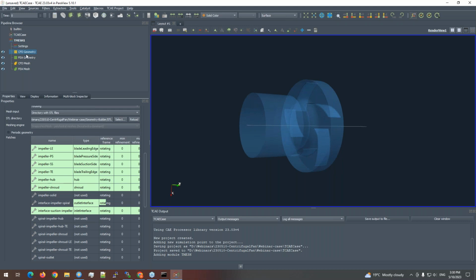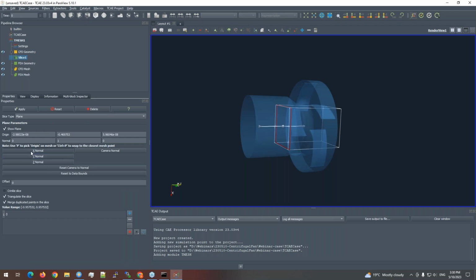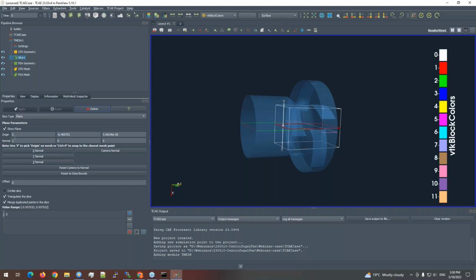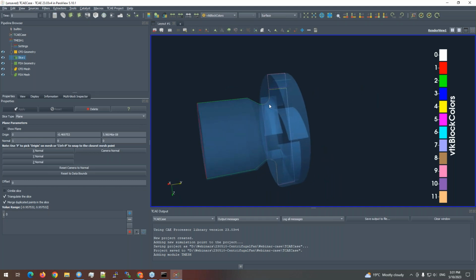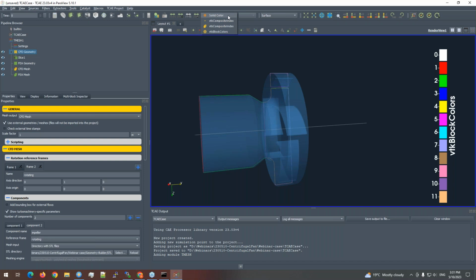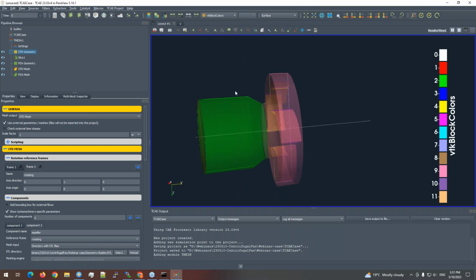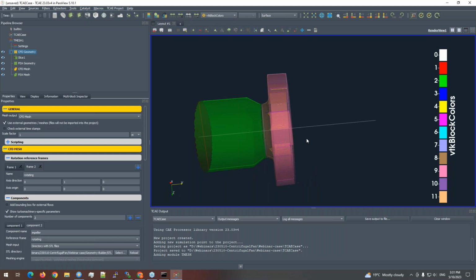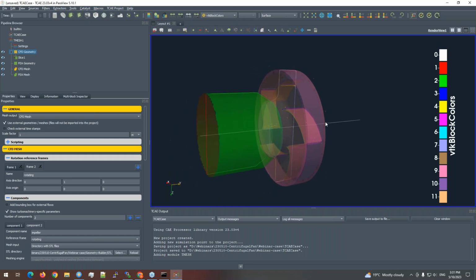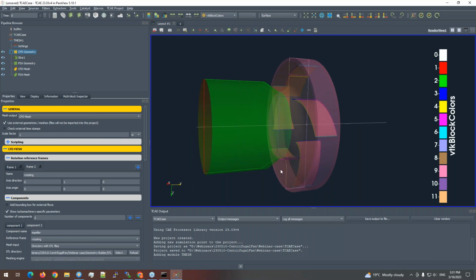What I also like in this geometry definition phase is that we can create, for example, the meridional contour of what I have already defined. We can click on the CFD geometry, click on a slice and create, for example, a slice perpendicular to the x direction, which goes through the origin. Now if I click apply, I can also see the contour of my current geometry, which highlights the boundaries which I have already preset. Here it's also possible to change the coloring. So you can change the coloring of each part you have already defined, so it's more representative that each part has a different color.